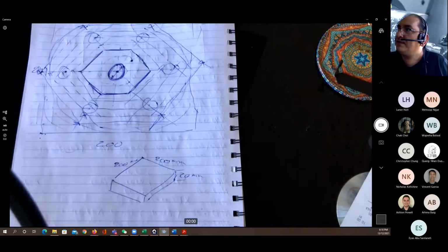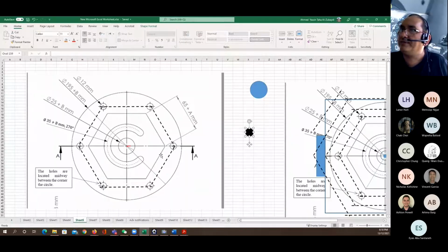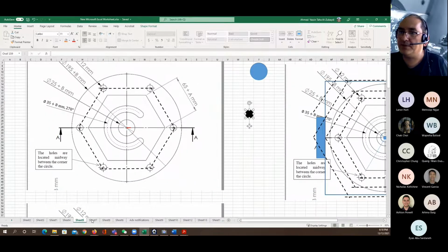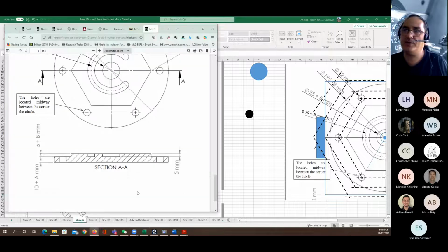Now there's another challenge we have in this work part. When I said that the thickness is going to be 15 millimeter, we have to remember that it's not recommended to cut 5 millimeter in a single shot, because this may damage my cutting tool, and it is also going to give me a bad surface roughness.